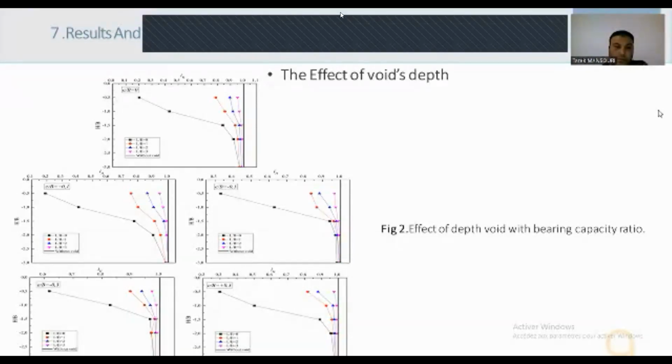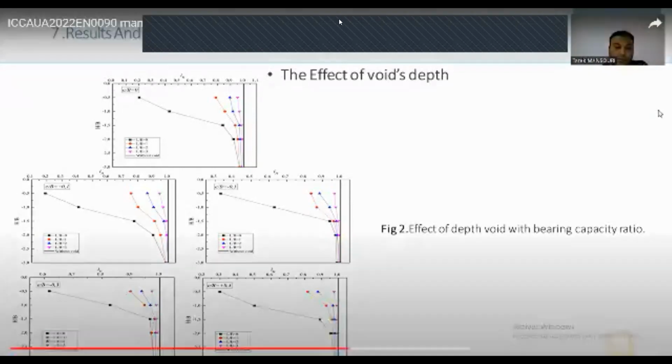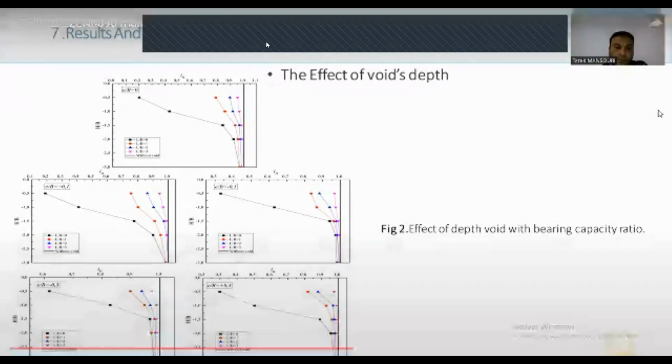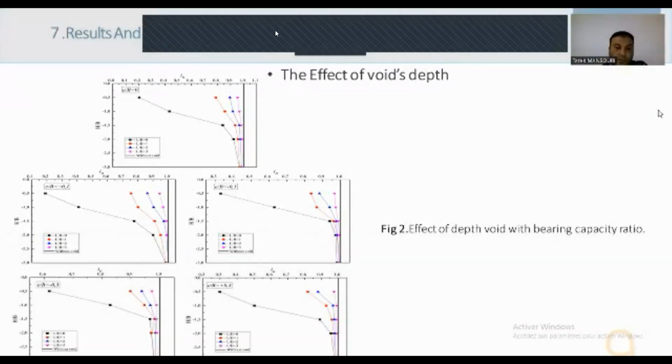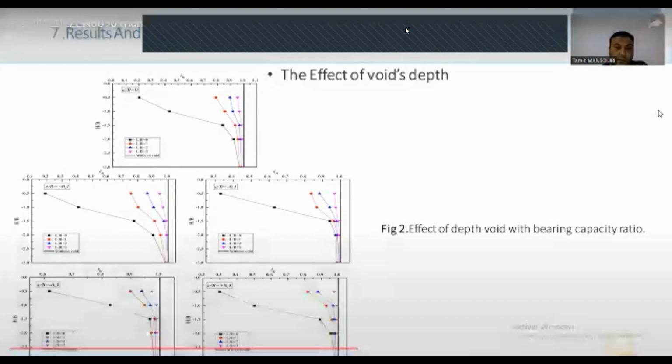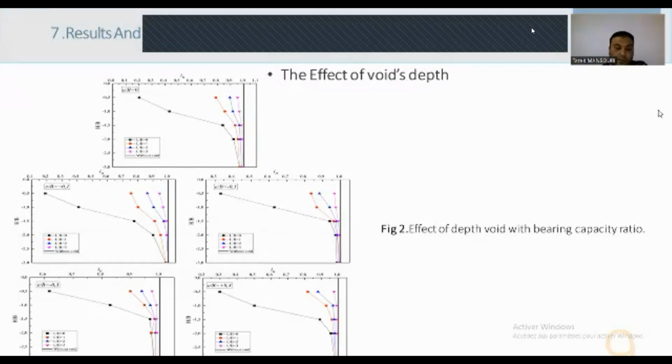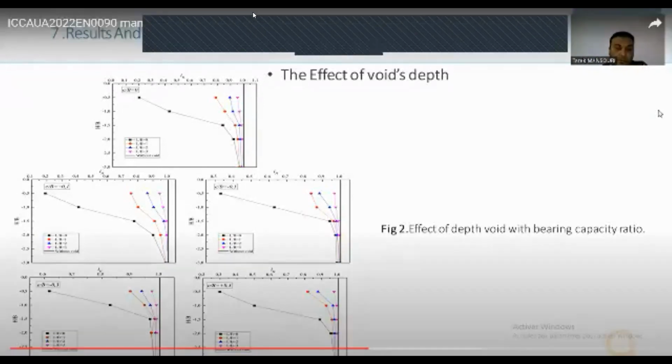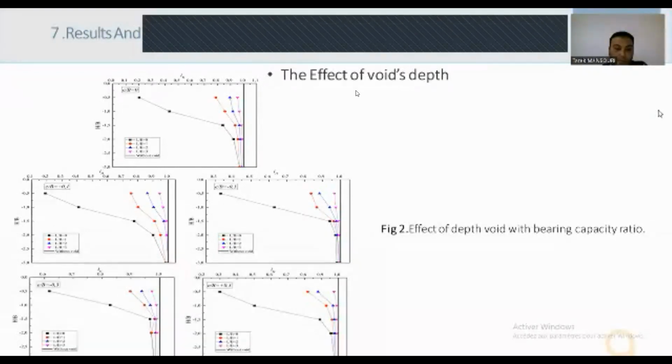A significant instability between the soil and the nearby voids had been observed when the void distances h on b and l on b were equal to 0.5 and 0, respectively. Consequently, the soil collapsed with an 80% reduction in the bearing capacity value. This occurred because the small distance between the footing and void, including the soil mass underneath the footing, was thin. Therefore, a low total shearing resistance was mobilized.